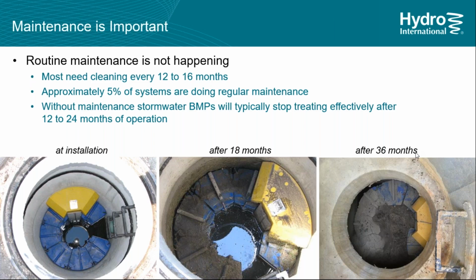And so when should you maintain your filter? We recommend an inspection after 12 months, and then you maintain as needed. So there's no one size fits all maintenance plans with these filters. It varies by site, but if you inspect after the first year, maybe you service after the first year, you say, oh, this could have been a bit longer. So then you do it 14 months later. And then if they still have a little more life in them, 16 months. And it'll take 2 or 3 maintenance cycles to really dial into when you should be inspecting and servicing.